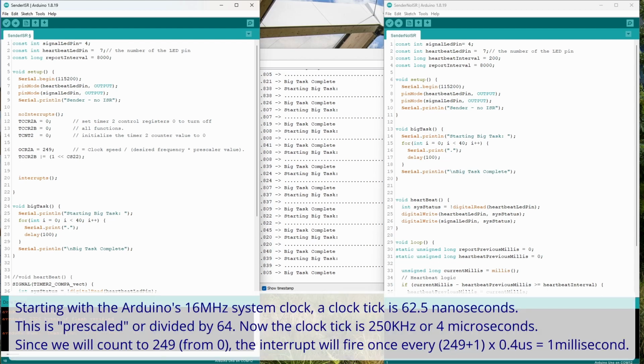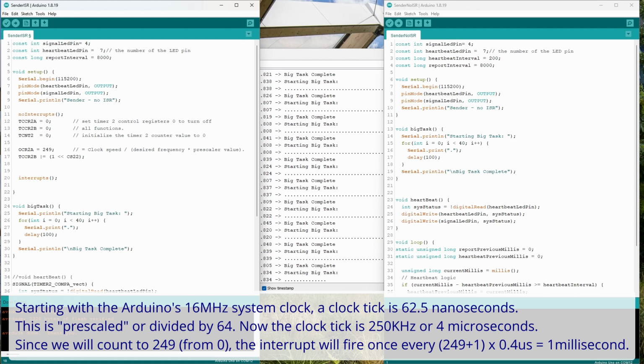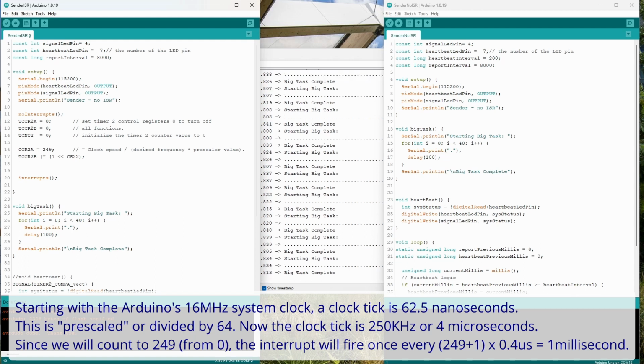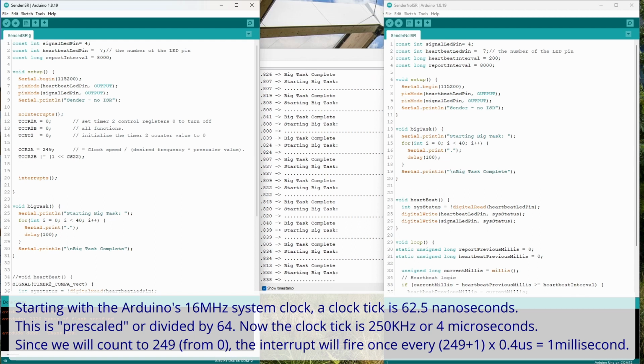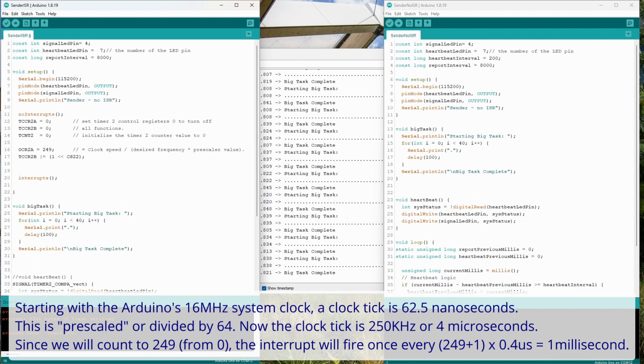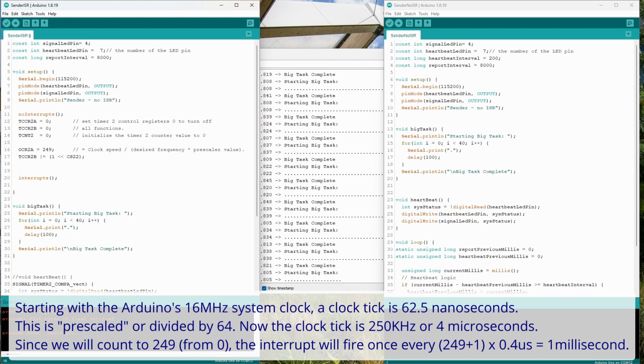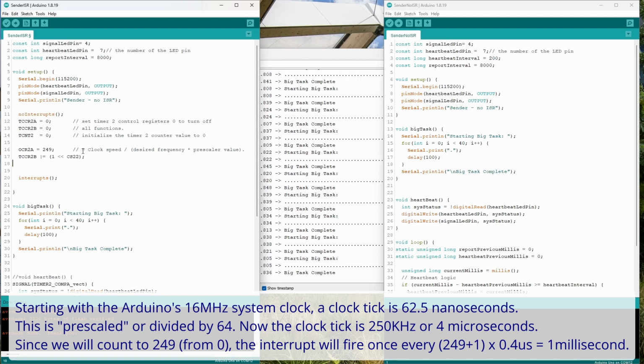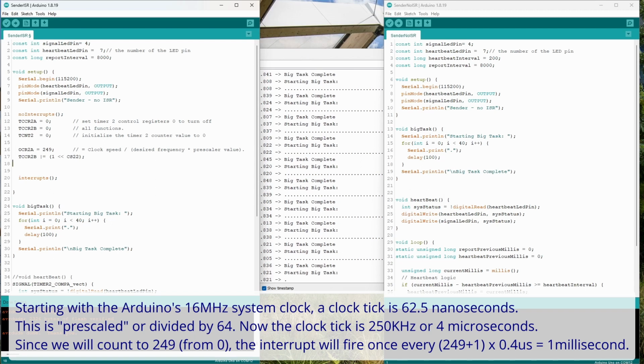This one sets a pre-scaler, so what it does is it sets the 64 times pre-scaler. What that means is the 16 megahertz clock is divided by 64, which means that the timer will increment 1,000 times per second when we include the counter match value of OCR2A.